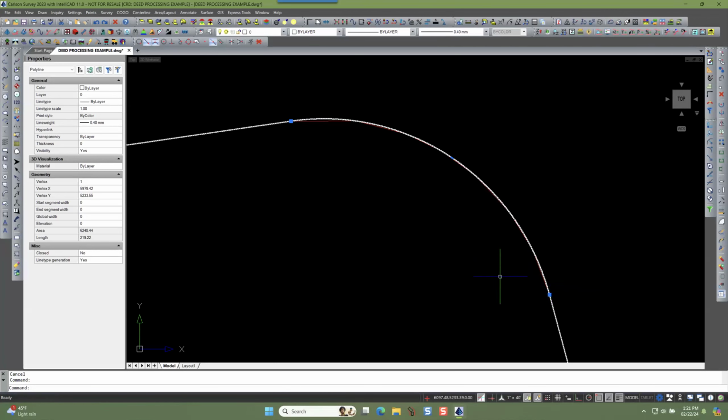So now when you're looking at the resulting thing that you've just created by pulling that point up in the air, and you have to look at it perpendicular to the plane that it lies in, well, it's no longer a circular arc. It's actually been stretched. But when we look at it in plan view in our drawing, we're looking at it still from the original plan view direction. It still looks like a circular arc, but it's not, and it can't be defined with differing elevations as any type of a thing because it's a stretched out arc.